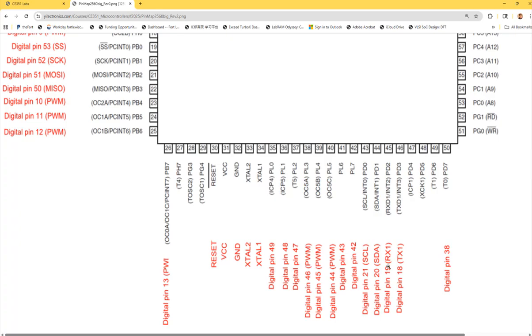RX1. So it's pin 45 from the manufacturer, from Arduino, right? However, whoever designed the board, they renumbered it as number 19, and Kai put these correct numbers on the board. So you wanna try to find out pin 19, and that's RX1, right? That's RX1.